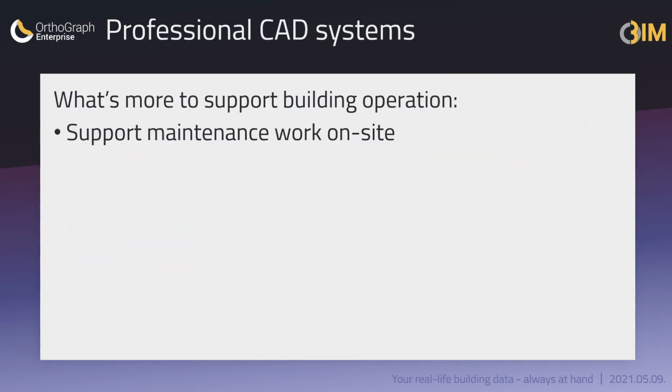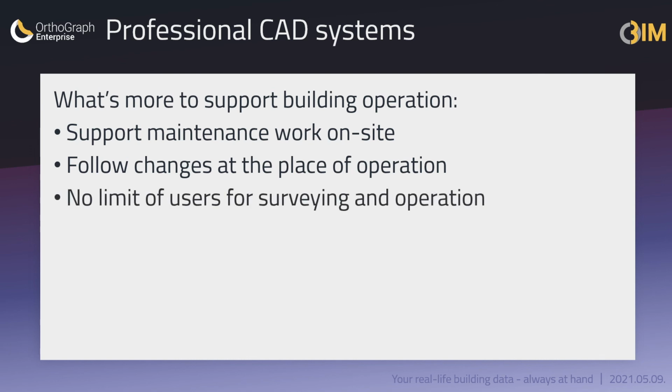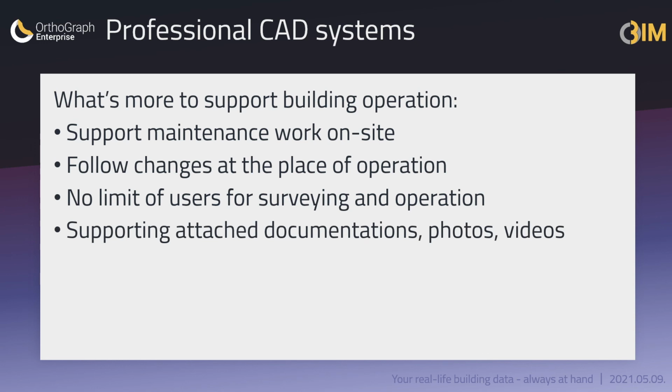The Operational BIM is all about a better way of facility and maintenance management. It's all about cost reduction, increasing service level and additional revenue generation. It's all about money. Maintenance workflows are supported with navigation, asset properties, and documentation instantly available at the place of work. And by using the model for data access, it's only a simple and easy step further to record all changes made during the work. This results in always updated building documentation. All this is done by an unlimited number of maintenance or technician crew. Photos made at the last repair will support the next events. Maintenance videos attached to similar devices will improve the work level while reducing downtimes.